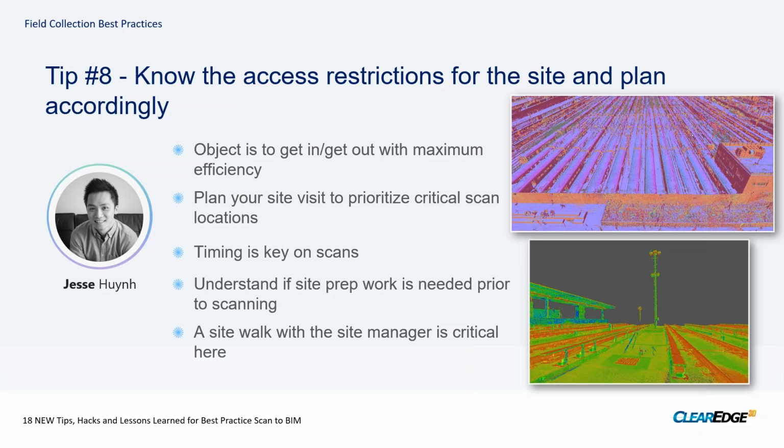You don't want to just distribute your scans evenly throughout a space if a particular section of the site is much denser than the rest of the site. Planning out where you're specifically scanning will save you a lot of time when it comes to actually being on the site and all of the activities going on.